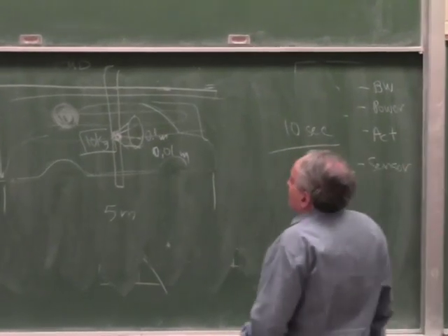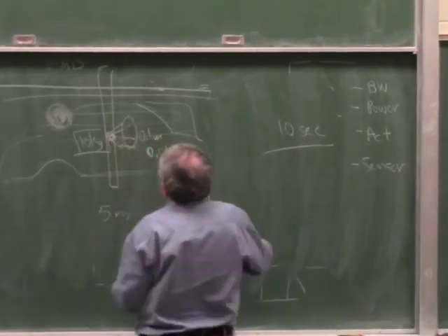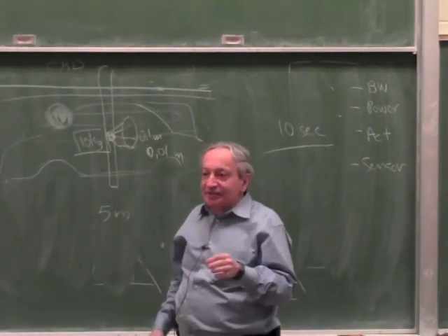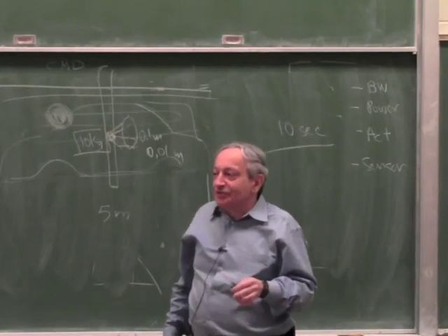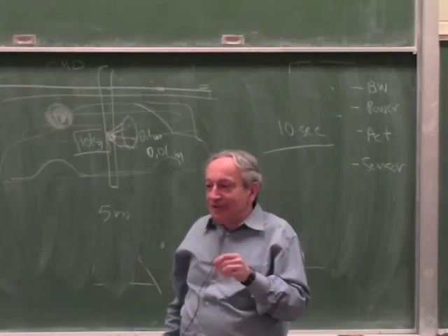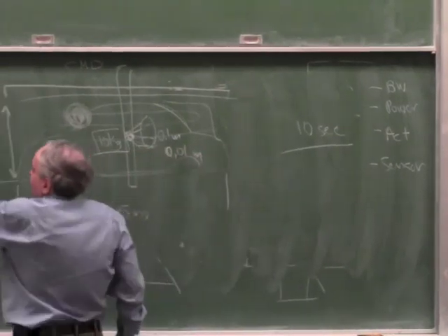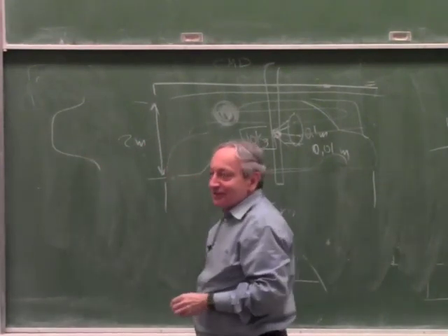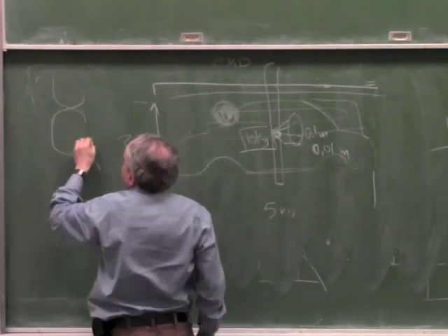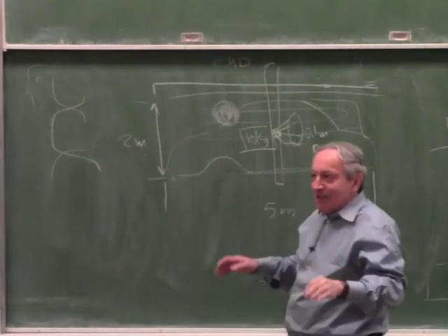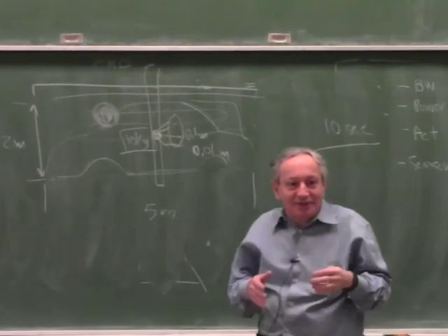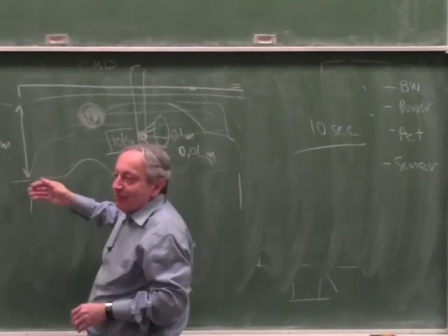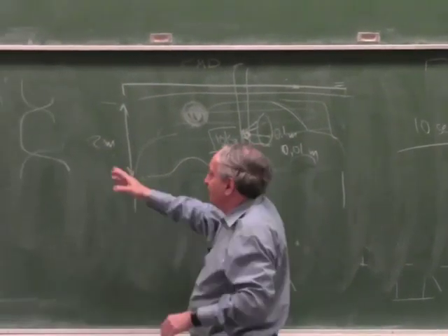Good. So if this is 2 meters, I have to cover 10 centimeters, okay? So I need at least 20 scans. If you are a good student, you will put a note that it's better to use 25 scans, because if you think of a spray gun, it's probably a bit like this, right? So probably you want to have some overlap just to get nice painting. If you really were designing it, not just for the exam, you'd say the minimum is 20, but it's very bad to leave a gap between scans, so let's make it 25.